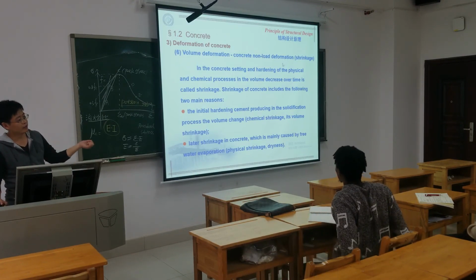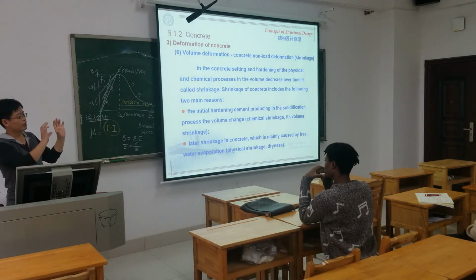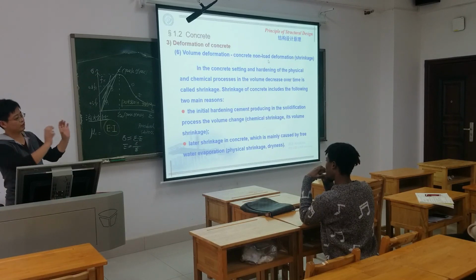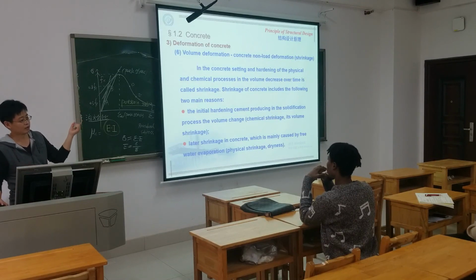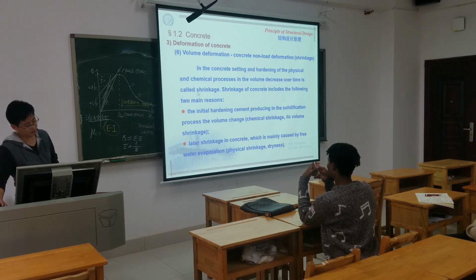Creep is under a situation with no change of load, but shrinkage is totally a no-load deformation, totally induced by the characteristics of the concrete. The volume decrease of concrete over time due to physical and chemical processes is called shrinkage.